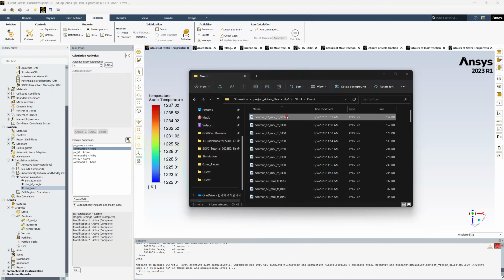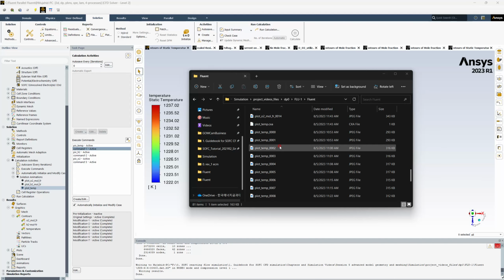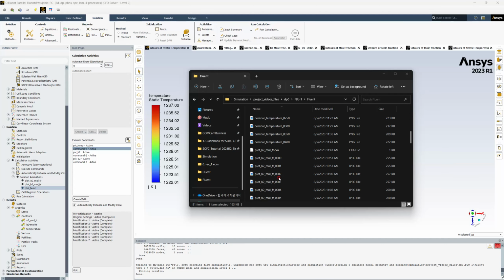Now you can see we have all the contour plots, and we can select them at different conditions. This is one of the most important parts of post processing, and that was automatically done when we were doing the parametric analysis. We can't get these pictures after we have done the analysis. It is really difficult to get back to a condition of 0.5 or 0.8 or 0.9 volts, but here we can get all the contour plots along with the final desired solution at 0.7 volts.